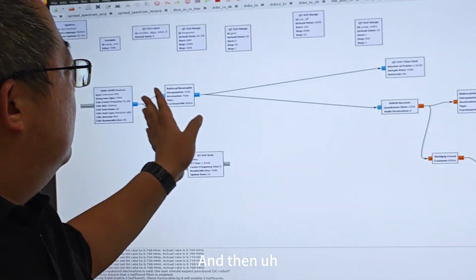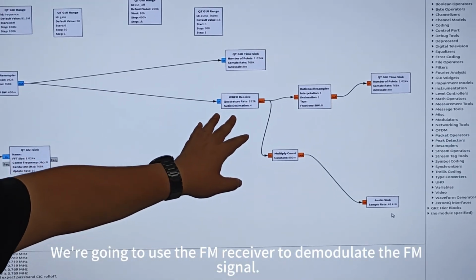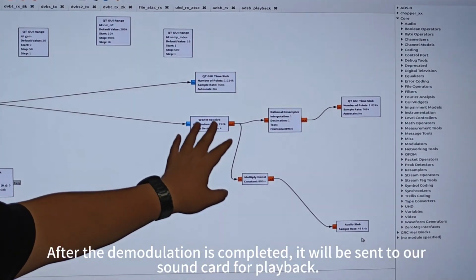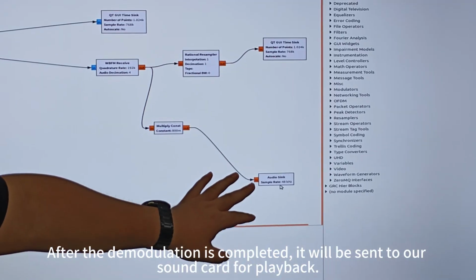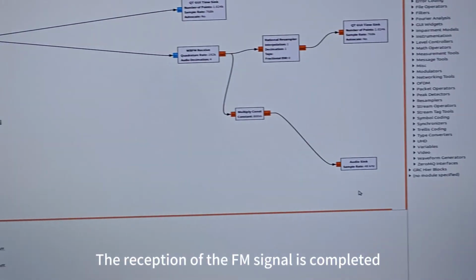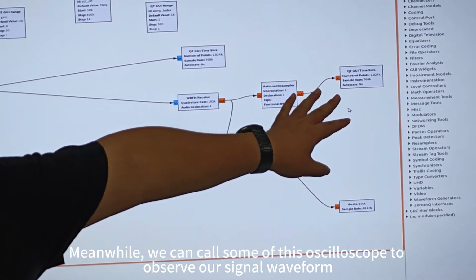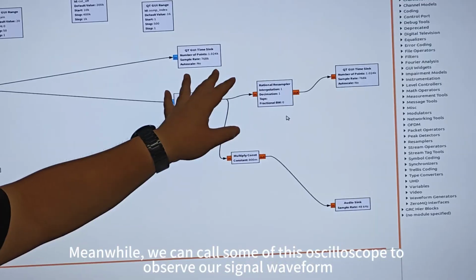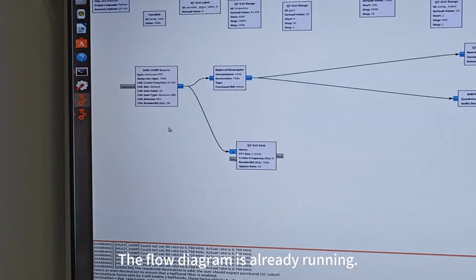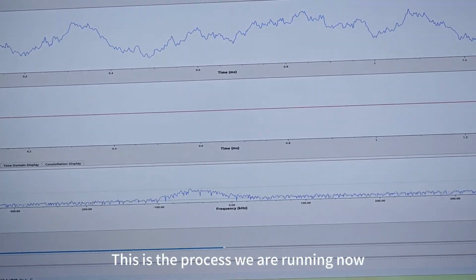And then, after the sample rate conversion is completed, we use the FM receiver to demodulate the FM signal. After the demodulation is completed, it will be sent to our sound card for playback. The reception of the FM signal is completed. Meanwhile, we can call an oscilloscope to observe our signal waveform. The flow diagram is already running. This is the process we are running now.